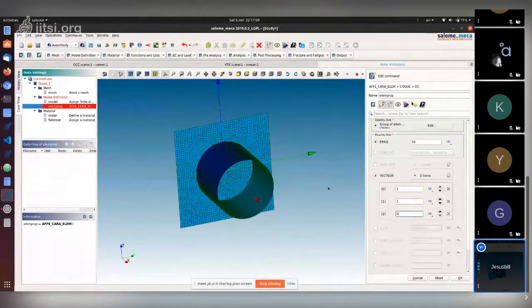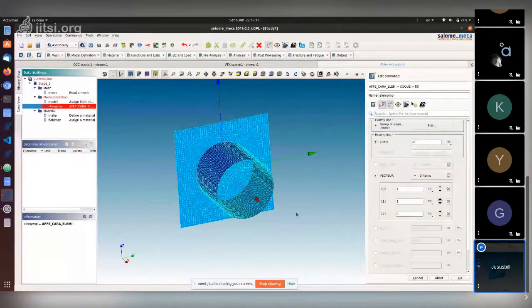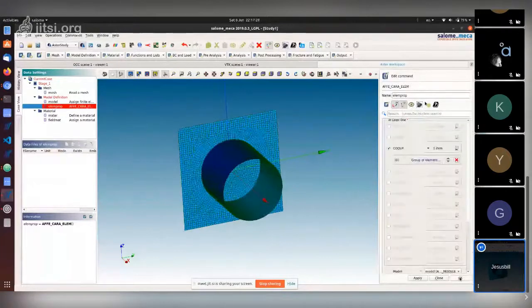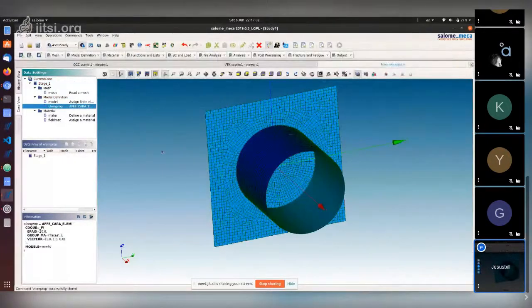So when you are looking also for the forces or the stresses that they have reference in local axis, you know where this local axis x is. If you don't define it, then it's going to be by default along the x-axis, but it should not be perpendicular to any face. So in this case, for the plate, it will give us an error, so we have to assign it. And by doing that, we have also the element.